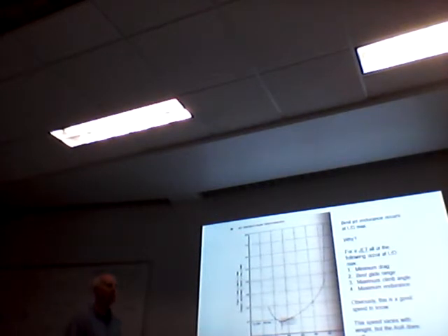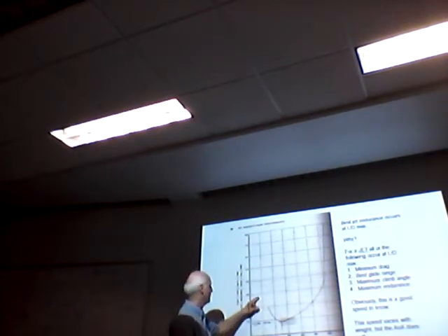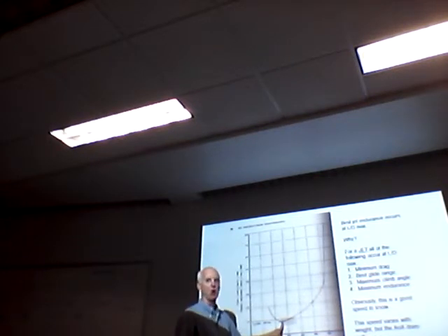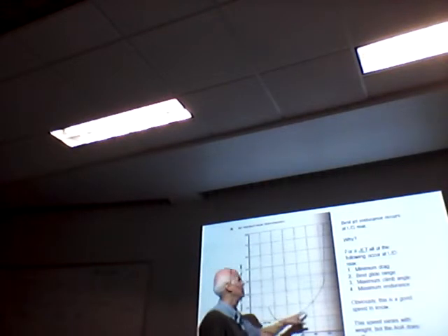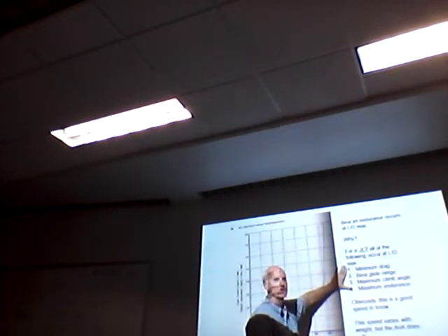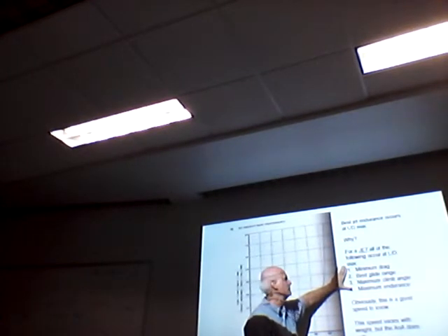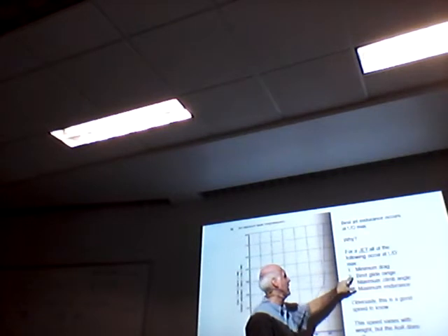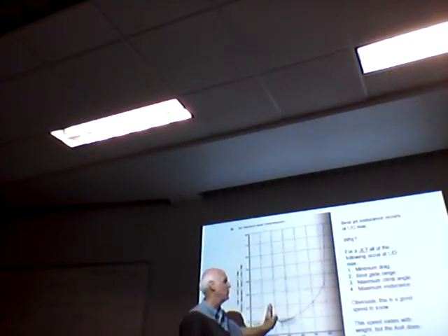This is important. Okay. The bottom of the curve, minimum drag for a jet, is L over D max. Not so for the propeller-driven airplane. We'll see later. But remember that these things happen at L over D max. Range, maximum climb angle, max endurance, those all occur at that point for jet aircraft.